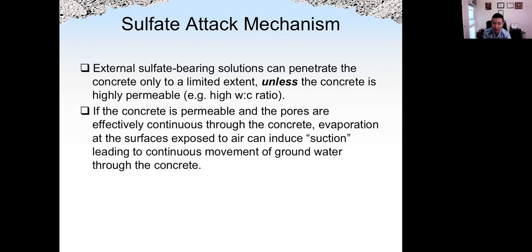If the concrete is very tight, it is hard for the solution to penetrate and do the damage. If the concrete is permeable, the pores are large, the porosity is high, and the pores are interconnected, that makes the solution easy to penetrate into the concrete.